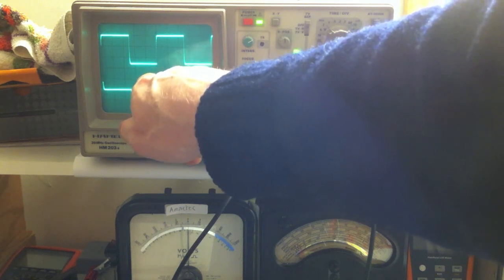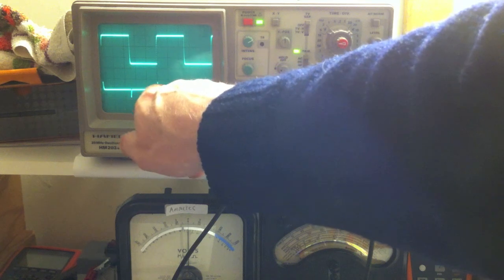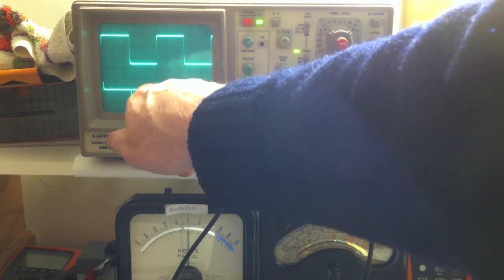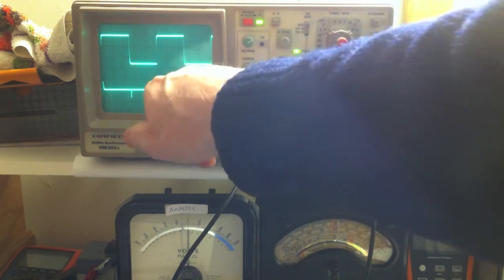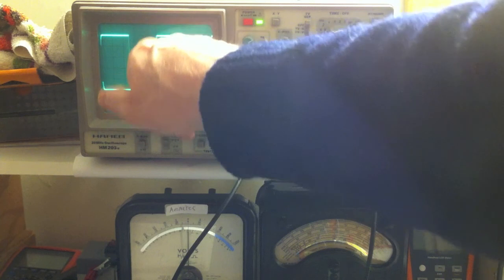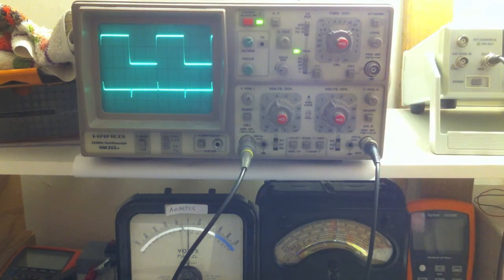You're going to be able to see that familiar discharge, what looks like a discharge of the capacitor. Basically it's the capacitor charging up, and obviously the voltage then is all dropping across the capacitor. So we can see that by increasing the resistance, because if we increase the resistance we're going to slow the current down. The more we increase the resistance, the slower the current becomes. Therefore we're going to be able to see this charging of the capacitor more clearly.